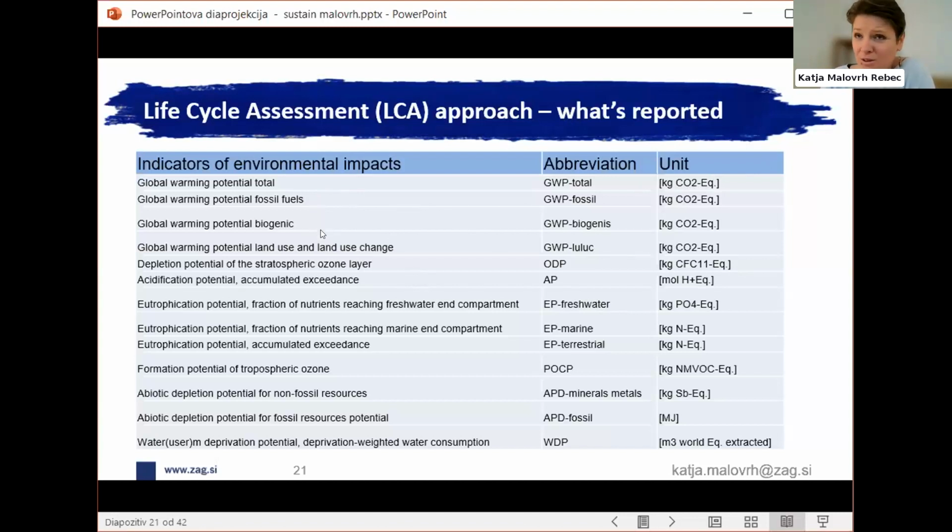That's because there is a tricky part in LCA methodology that we call sequestration, where materials like wood are treated as materials that can actually store CO2. Usually we calculate LCA for 100 years, and wood can be used, especially if we use it in a cascade manner, for longer than that.